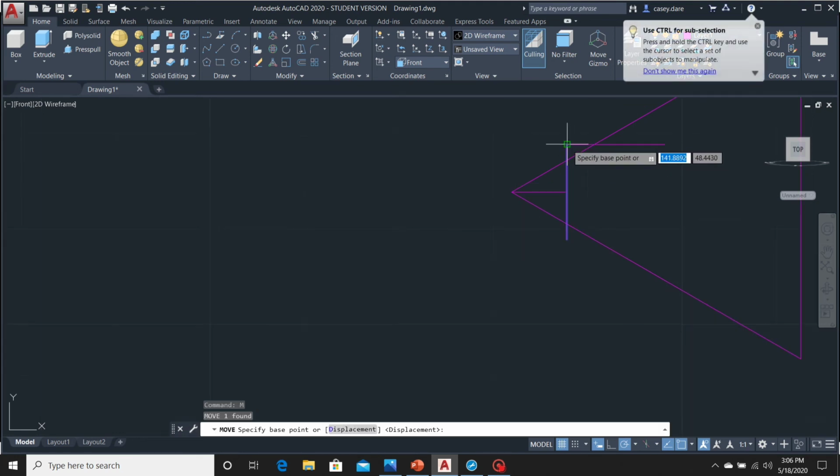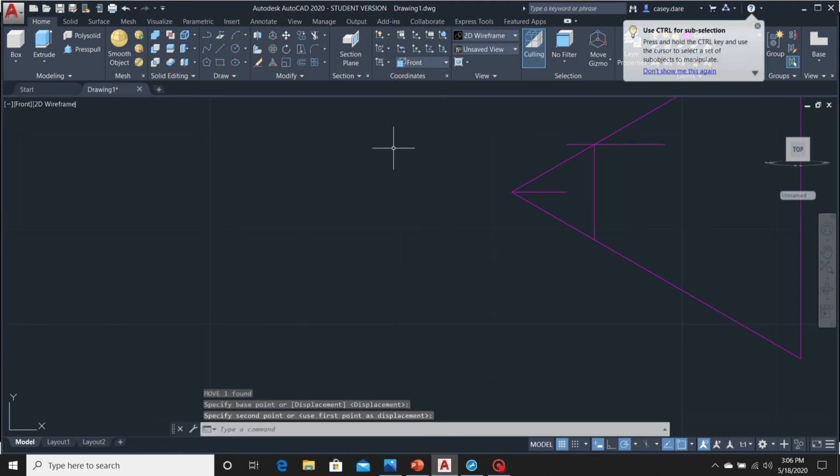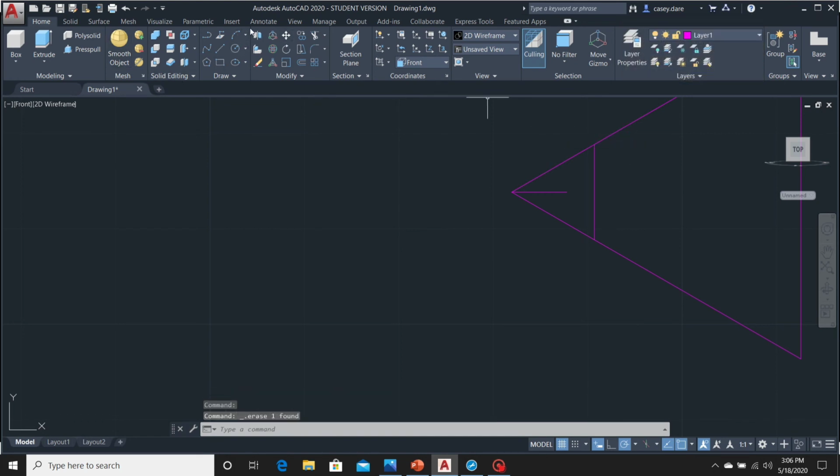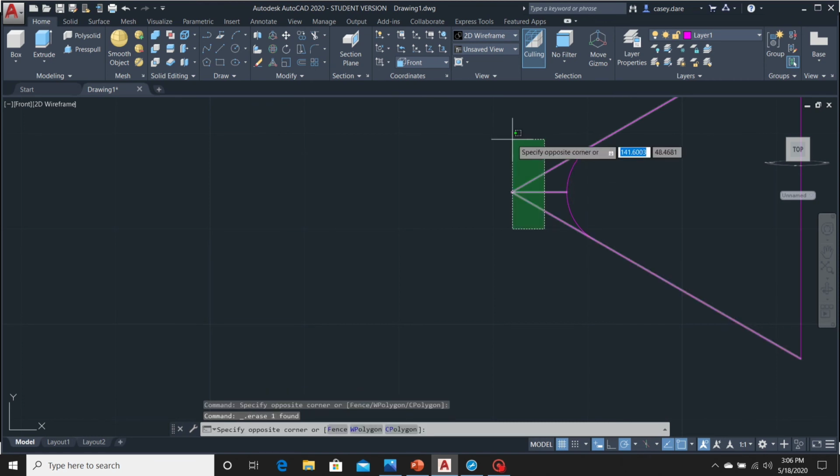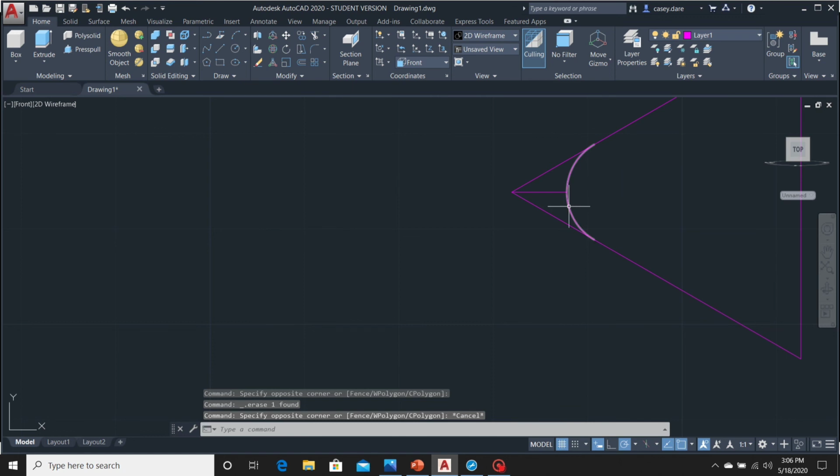And this should give you the 3 points to make the fillet for your cutout piece. So now we'll go up, pick the 3-point arc command, and connect our points. And from there, we can go on to trim up our tool.